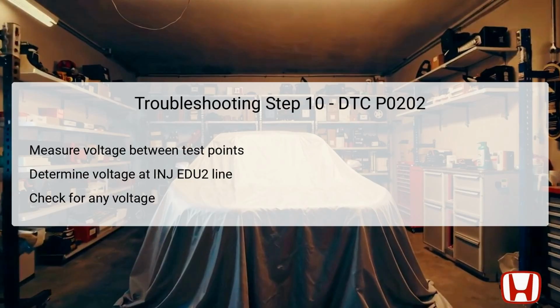Continuing with Step 10, you will remain in the off-lock mode. If necessary, ensure to remove the jumper wire from the injector relay 4P socket and reconnect the connector for the injector control module D4P. The next step is to measure the voltage at injector control module connector D4P, number 2, while referring to a good body ground. This test verifies the integrity of the INJ-RLY out